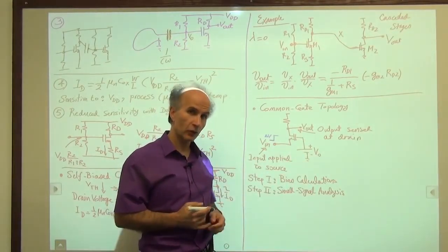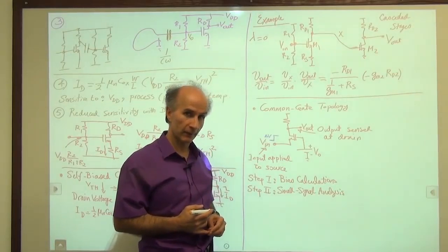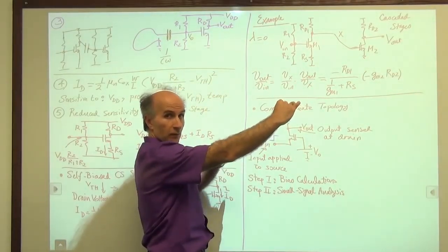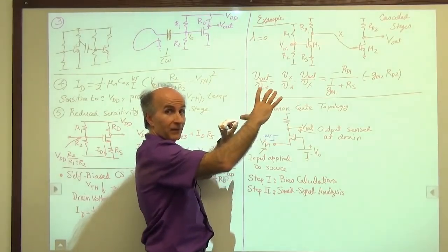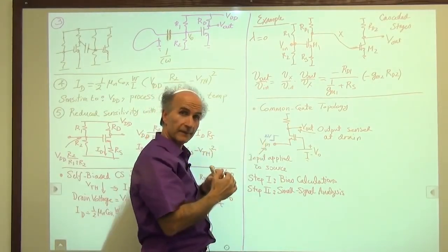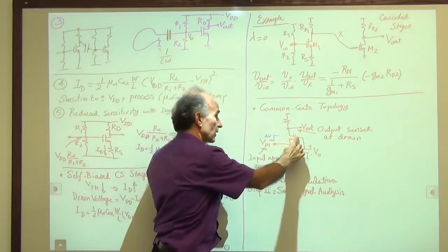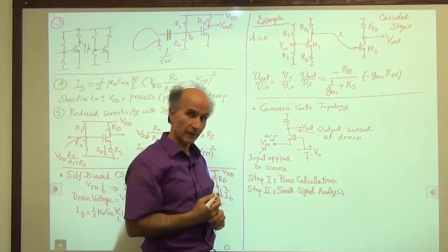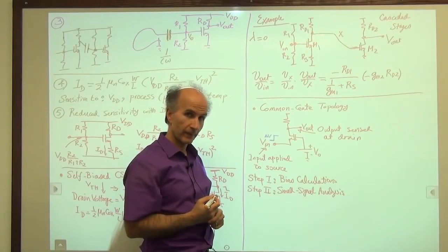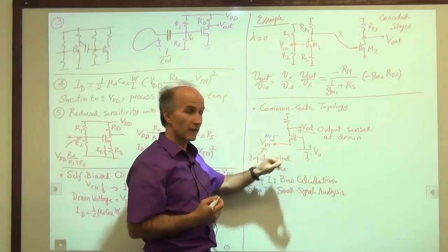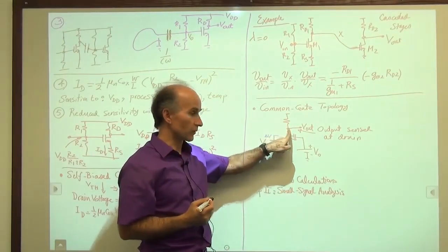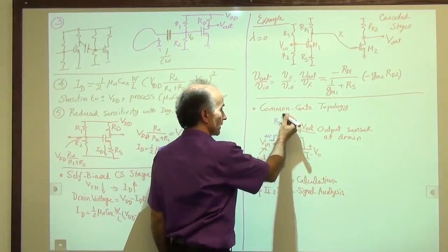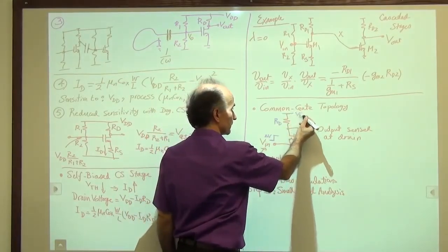All right. And remember that the gate voltage is constant. So what happens to the drain current of the MOS device? The gate voltage is constant, the source goes up. That means that VGS decreases. If VGS decreases, the drain current decreases. If the drain current decreases, what happens to this voltage? So we have a resistor here. We have VDD here.